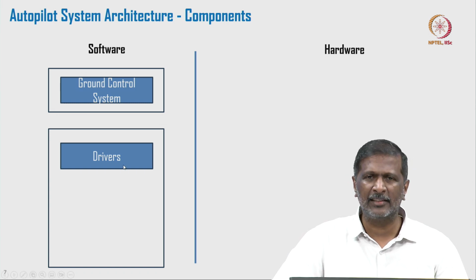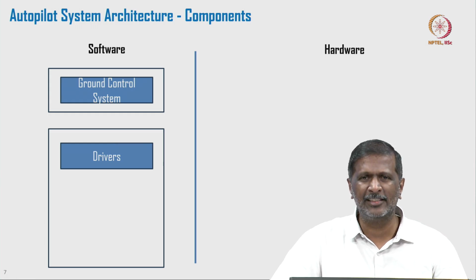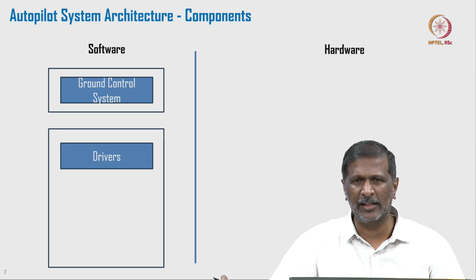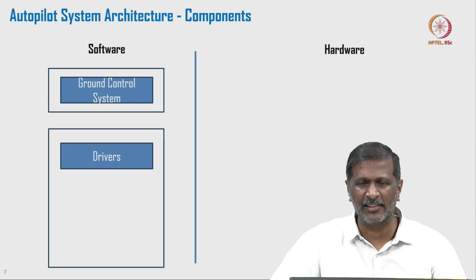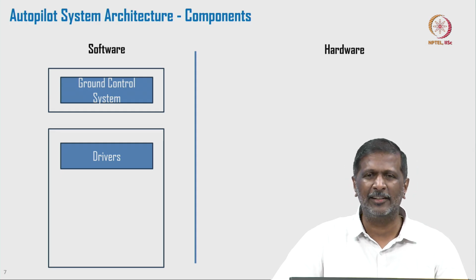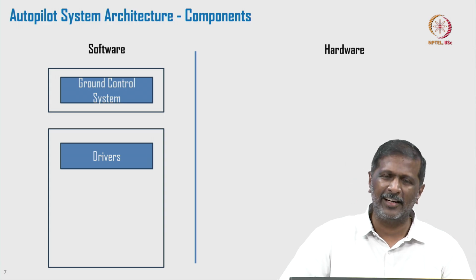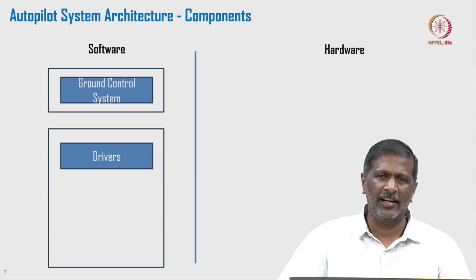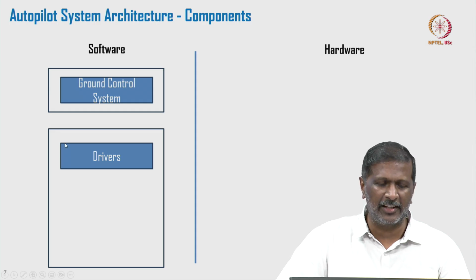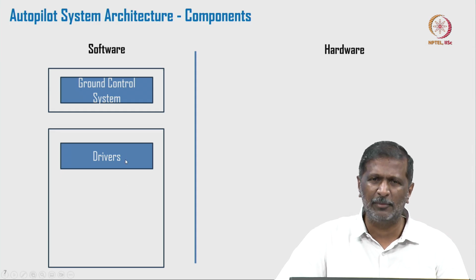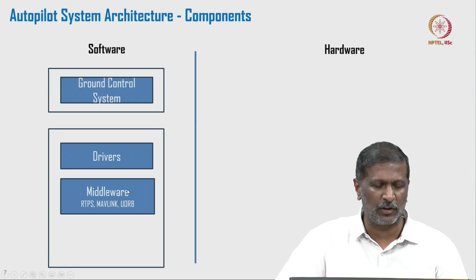All that requires conversion from your flight control to a digital signal, which goes to the electronic operation, and is converted from that into an electrical signal and sent to the motor, or getting an analog signal. And you have an ADC which converts into digital, you need to read, you need a specific communication mechanism. Those are the drivers we are talking of.